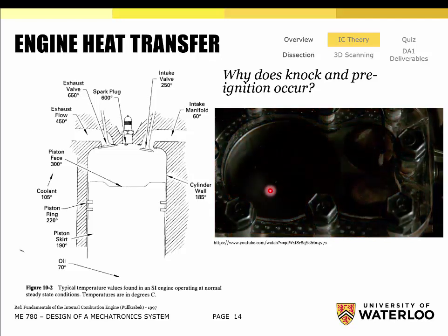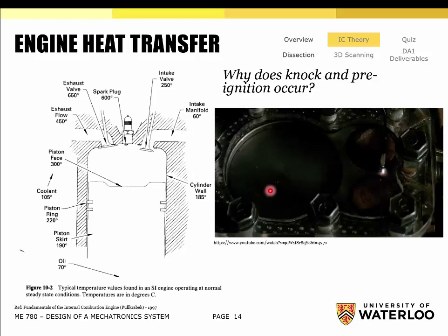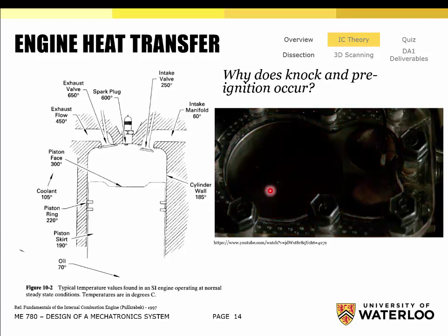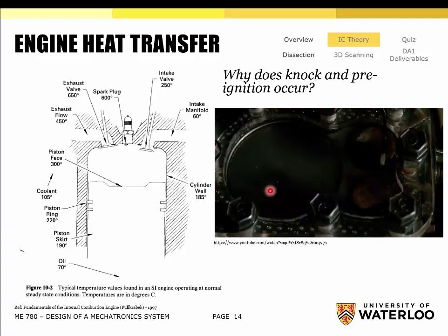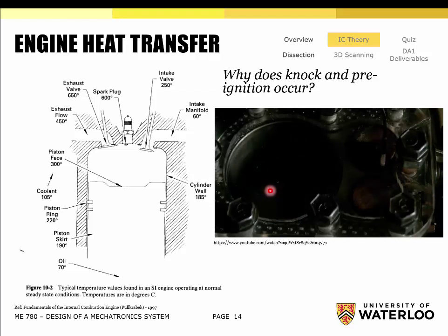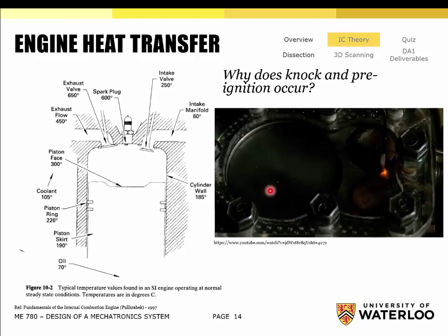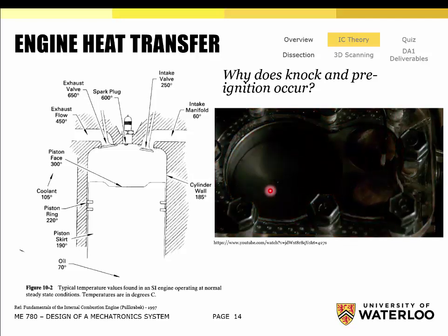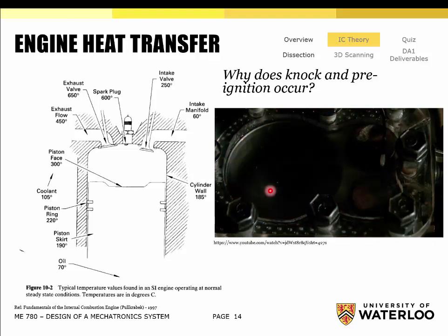ignites. I want you to really look at when you see that little spark, okay? Let's go back. So you're gonna see the spark fairly soon here. Okay, in the next cycle you'll see it. So does it happen before or after top dead center here? So the piston's coming up. So did it happen before or after the piston reached top dead center? I see some saying after, some saying before.